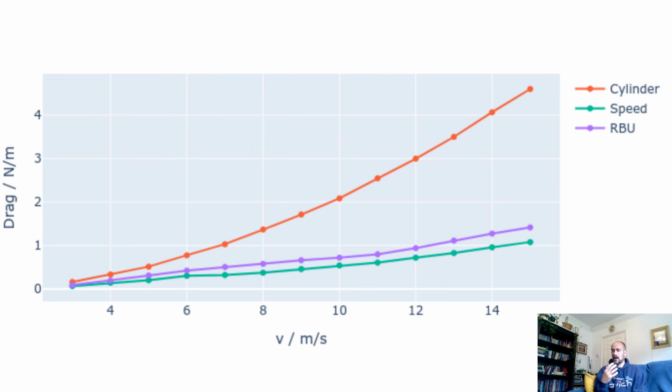What this graph does show quite nicely is just how much lower drag the aerofoil sections are than the round section. As I say, we don't actually offer the round sections anymore. Our basic gliders have the rubber back ones. But you can see that compared to a round section, well, the round section is about 4 times more drag than the speed section. The rubberback section is about 30% more drag than the speed. And bear in mind, this isn't going that fast either. This is only 50 kilometers an hour. And obviously, the faster you go, the more penalty you're paying for that increased parasitic drag.